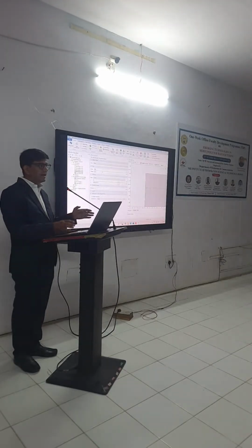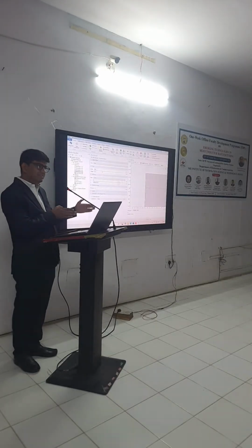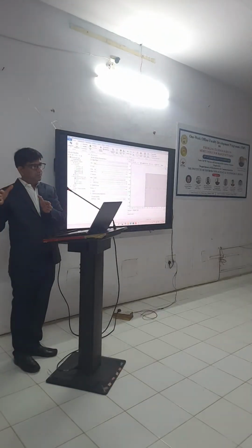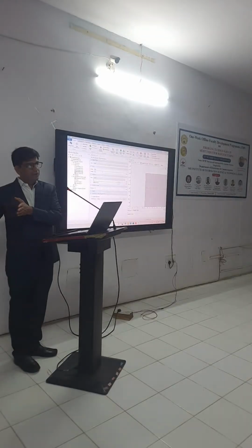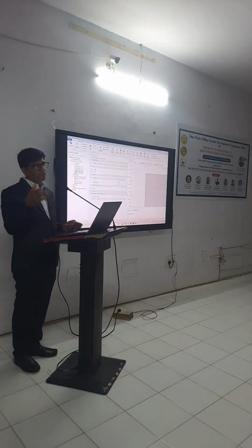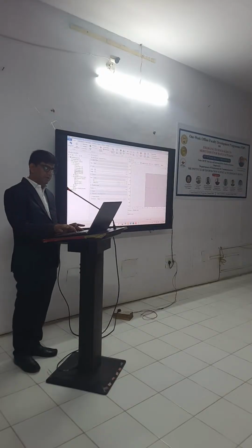So 250 I have to reduce, 125 from the left hand side and 125 from the right hand side. So from where do I need to start? I need to start from 125 micron. So instead of 0, I will select 125, and then I will click on build all.